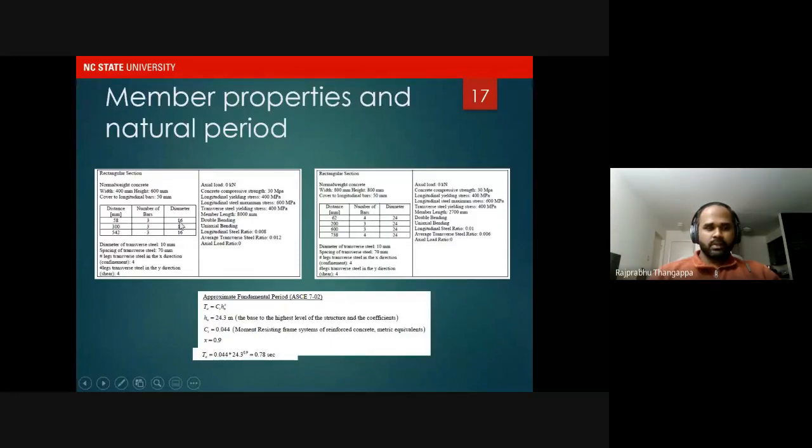And we have chosen 16 mm diameter bars and a reinforcement ratio of 0.75% would result in this pattern of reinforcement. And the distance you see here is basically from the edge of the beam. So the depth of the beam is 600 mm and the distances 58, 300 and 542 represent the location of the reinforcement from the respective ends.